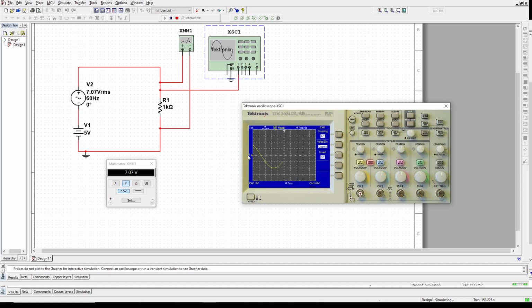Okay. Now let's see, because remember we were talking about peak-to-peak value and peak value and RMS value. All right. So here's the ground level. How far does it go up? 5 volts per division. So let's see. 5 volts, 10 volts. It reaches 10 volts. So the peak of that is 10 volts. The bottom peak is what? 2 divisions times 5. Another 10 volts. So we have 20 volts peak to peak.